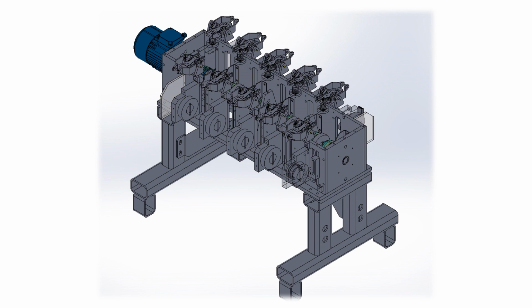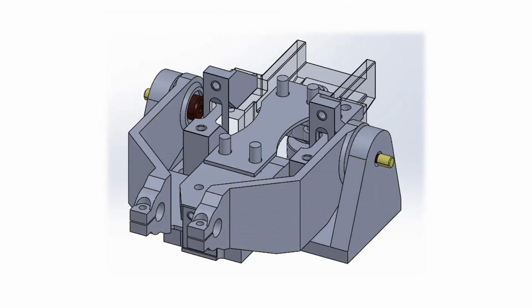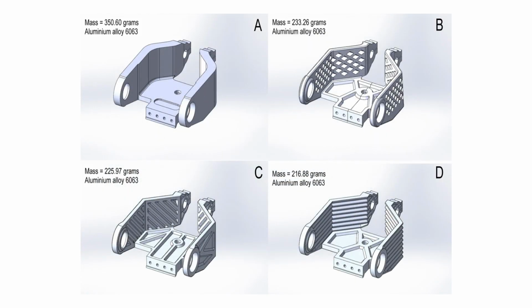Another example is the design of the rocker arm of a bending fatigue machine. This example utilizes topology optimization and generative design software. The design of the bending fatigue machine has redesigned the approximately 50-year-old Carl Schenck bending fatigue machine so that the new machine can fatigue 10 bending fatigue specimens at the same time. The design has utilized traditional design, FEM calculation, topology optimization and generative design optimization. The material chosen is aluminium Al-C10Mg.